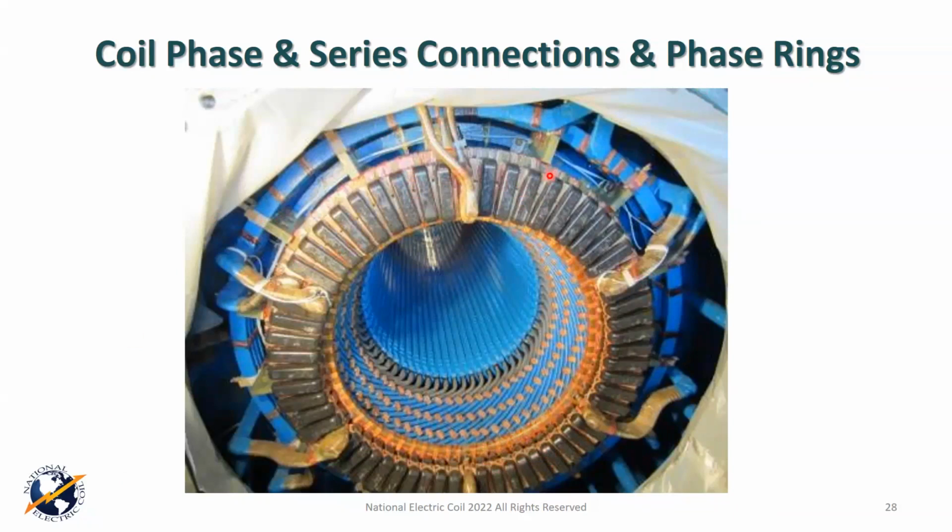Now on the back of the end winding, we also have some surge rings. And it's hard to see it here, but it looks like they're on lands on those brackets. So that would allow this end winding to move in and out from the expansion and contraction of the machine. So that kind of shows you everything that we've been talking about all in one nice, neat package. Obviously, this is before painting. And so that's kind of important.